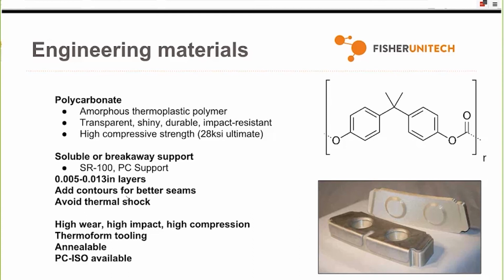So Stratasys measures impact resistance in two ways. They're both called IZOD tests. There's an unnotched test where a test part basically just gets smacked by a hammer. And then there's a notched test where that happens, but beforehand, a little chip of the material is taken out, and then it's smacked with a hammer. So in polycarbonate, cracks propagate very easily. So once you've established that little crack propagation nick in the side of it, it doesn't do any better than ABS or ASA in those notched IZOD impact tests.